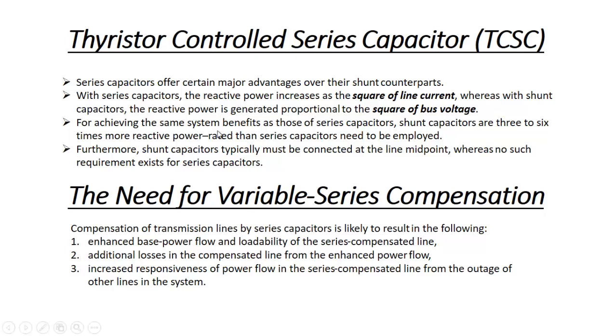For achieving the same system benefits as those of series capacitors, shunt capacitors rated 3 to 6 times more in reactive power need to be employed.